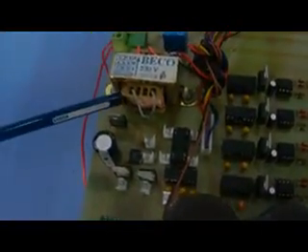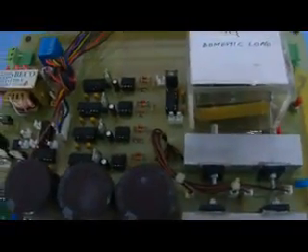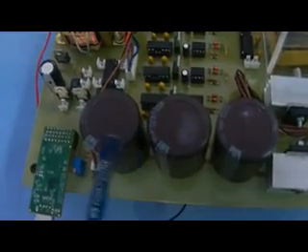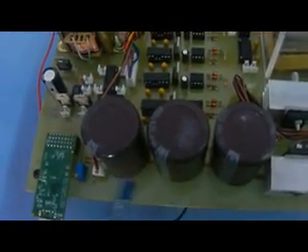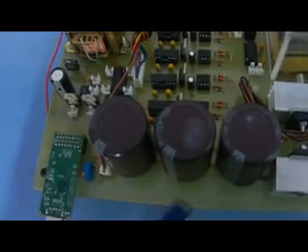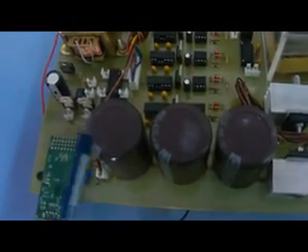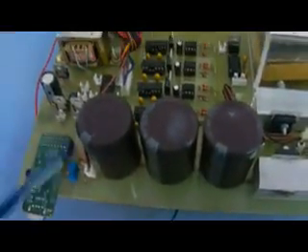Power supply section: by means of the step-down transformers and the rectifiers, a DC voltage is generated for the ICs and the voltage regulators. DC link capacitors reflect the reactive power taken by the system. As long as this voltage remains constant, power quality is maintained and the source current remains sinusoidal. The MCU or the microcontroller unit generates the control pulses for the switches by taking the DC link voltage and the source current as the inputs.